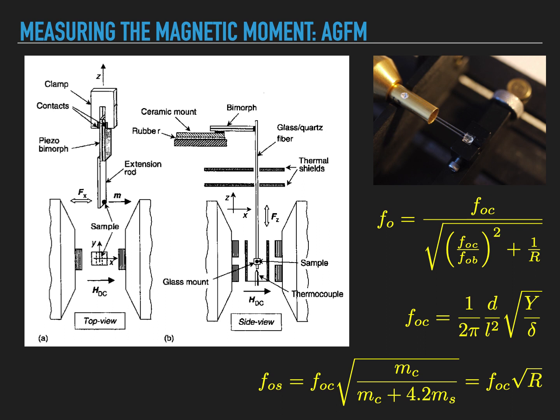The piezoelectric transducer will give as an output an alternating voltage that can be amplified and used for measurement. In order to make the magnetometer as sensitive as possible, resonance conditions are chosen.